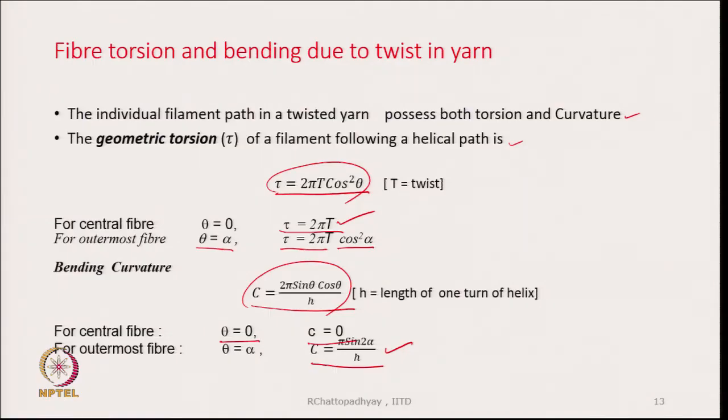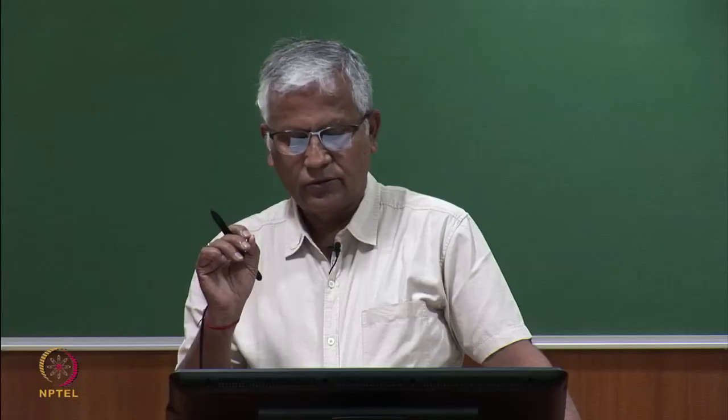So, when a yarn made from these fibers is twisted too much, the center filament will be extended, and torsion is going to go beyond the critical value, and therefore there could be some amount of damage to these filaments. Generally, you will find that yarns made from high tenacity fibers are not twisted much. They are given only very little twist, not much twist.